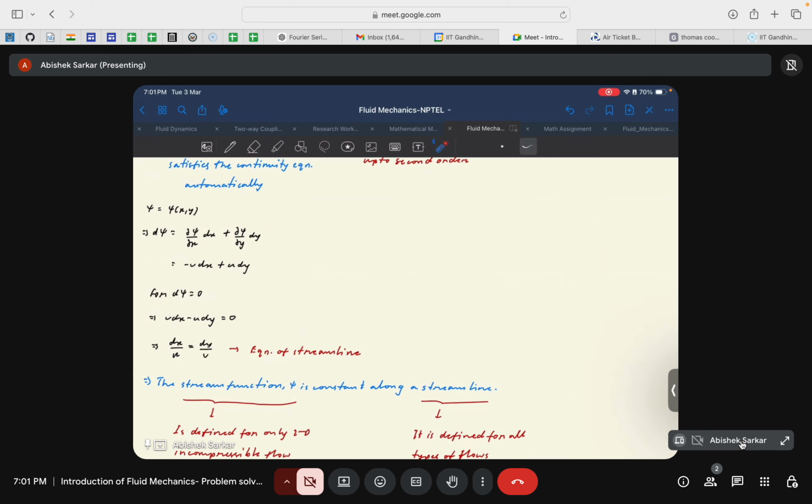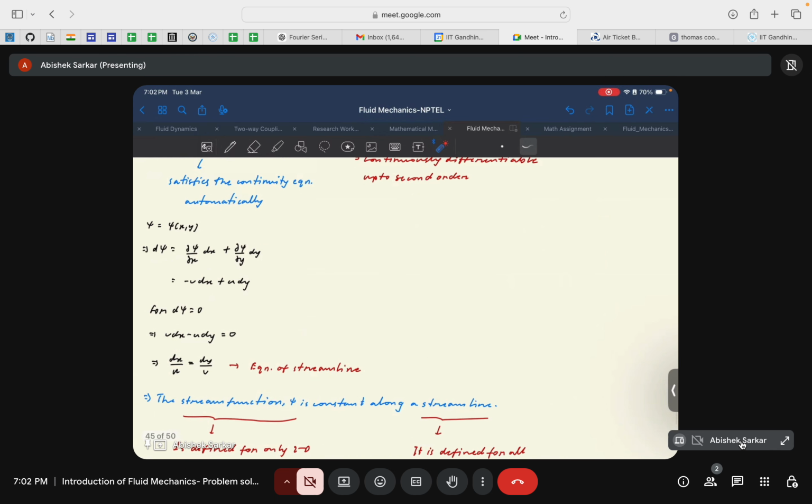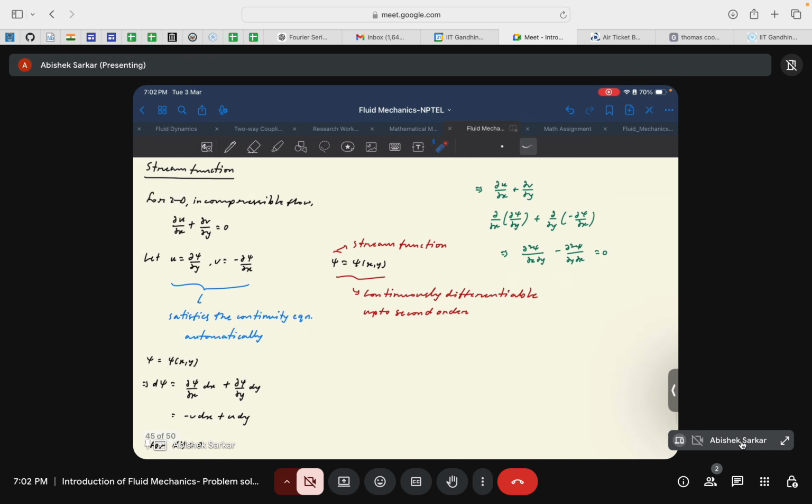So of course it is solvable, but it's quite hectic because you're dealing with three independent variables, P, U and V. Which is quite a tedious task from the start. Okay, it's a very tedious task to do. So by defining the stream function, you simplify your scenario very, very much. Like if you just look at the continuity equation, rather than dealing with two different variables, you only have to deal with one variable, psi.